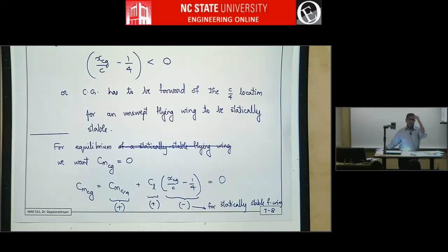And if you turn off this stability augmentation, this airplane might be pretty difficult to fly. It's not impossible to fly. Marginally unstable airplanes, people can still fly. There are other conditions that have to be satisfied, but it's a lot of pilot workload.